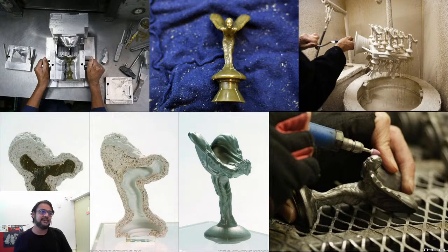It's made using investment casting. You would make a wax model, you would finish that wax model, and this is a very good image. It shows a cross section of the layers that are built in, and you can see the layers that are there, right? There's a thinner layer, a thicker layer, and slowly, at the top, there's a stucco layer, and once this is fired, this is what is seen.